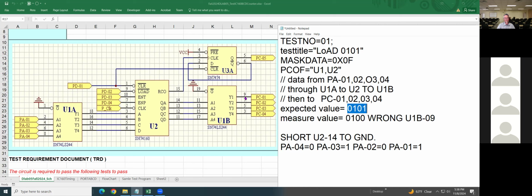However, if pin 11 you get it right, then what can you do? Oh, I see. Like we said, you have to check U1 pin 19. If pin 19 is grounded, then pin 9 equals pin 11. If it's not grounded, that means they're not equal.